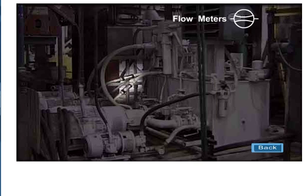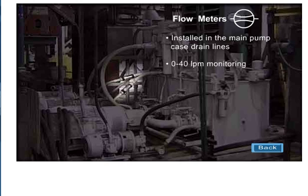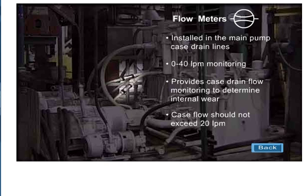Flow meter, installed in the main pump case drain lines. 0 to 40 liters per minute monitoring. Provides monitoring of the case drain flow to determine internal wear. The case flow must not exceed 20 liters per minute.